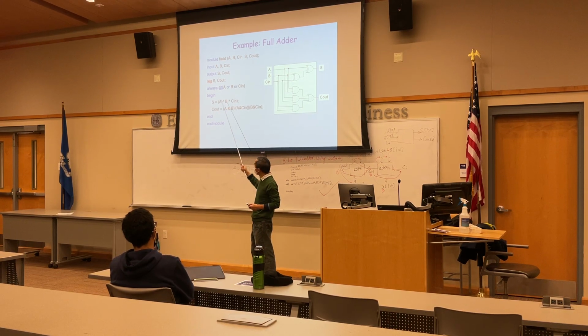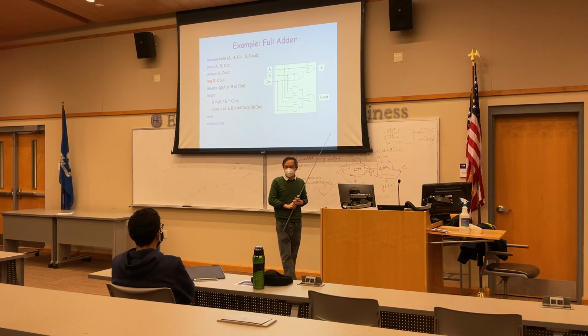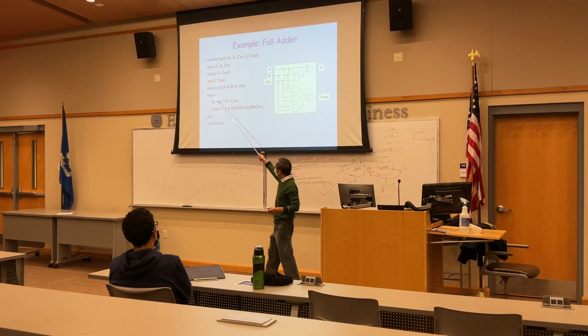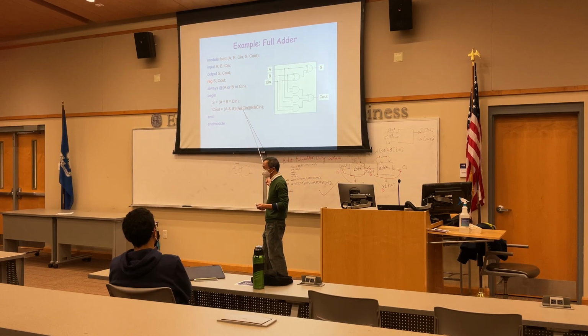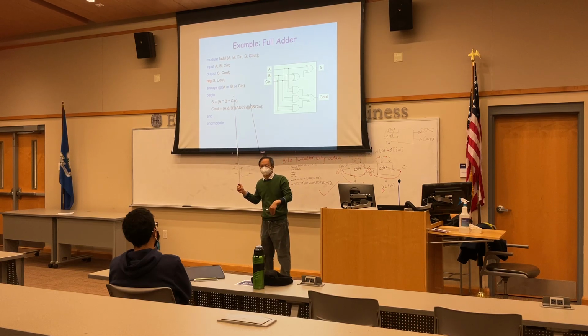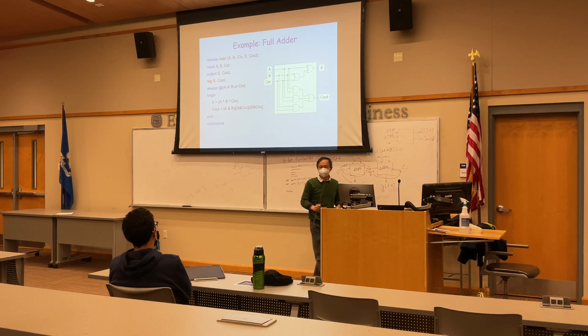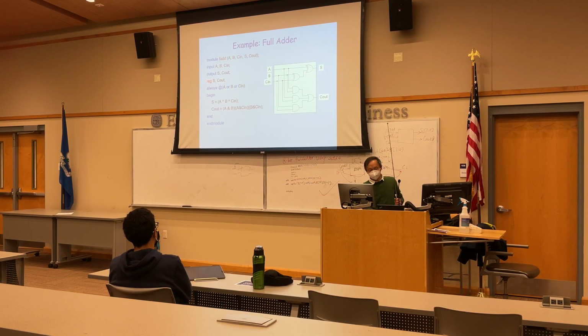An always block is a sequential statement. It's usually one by one, and this is like the process in VHDL. For example, in the class we have homework 1, homework 2, homework 3, homework 4. Sequentially, we group them in an always block, with a sensitivity list of the inputs.